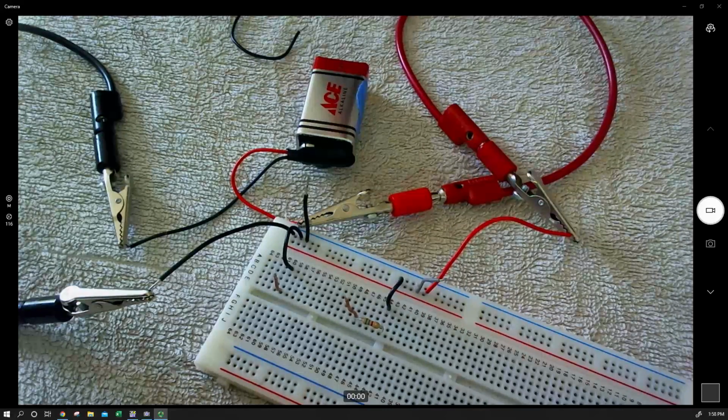Now, that doesn't mean that our load circuit doesn't follow Ohm's law. Basically, the amount of current flowing through our load resistor, our load circuit, will be defined by Ohm's law. So we'll take the voltage of our source, divided by the resistance of our load circuit, and that defines the current. Where the advantage of a parallel source comes in is when the load resistance is so low that the internal resistance of the sources becomes dominant.